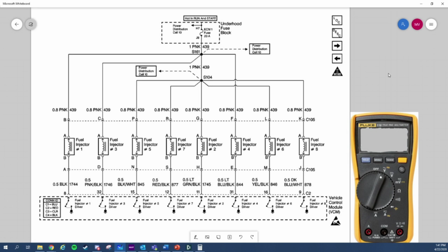So look at it, study it. How can I disable my fuel injectors? And what would you do and why? Pulling the ECM1 fuse. Okay, perfect. Why do you want to pull that one out? Because they're all connected to that one, connected to every single injector.